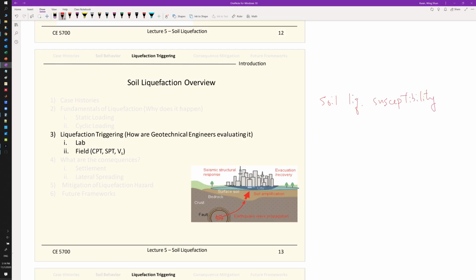susceptibility. So first we check whether the soil is susceptible to be liquefied or not, because liquefaction is for sand, right? And if it's a clay, then we don't worry about soil liquefaction. And it comes to tricky when you have silt, because silt is between sand and clay. So that would be the bottom line case that you need to spend extra effort to investigate whether it is susceptible to soil liquefaction. So we talk about the susceptibility maybe 2 slides later.